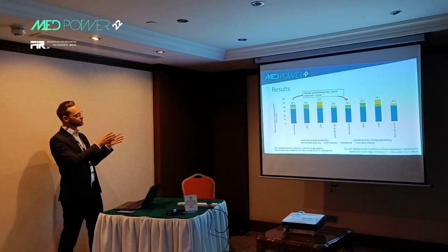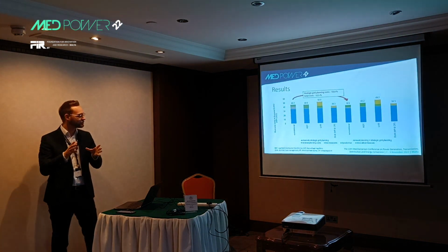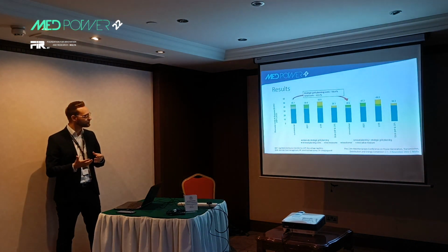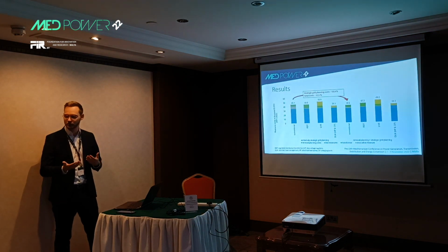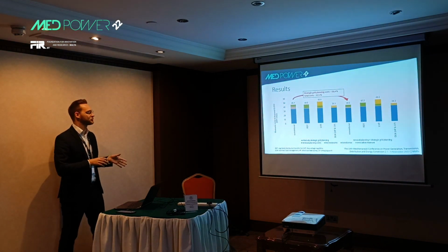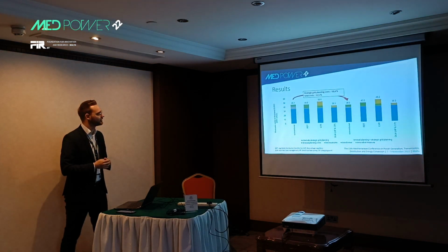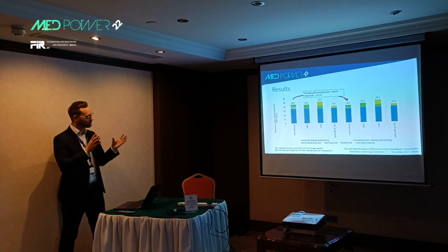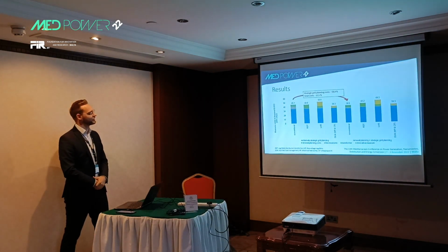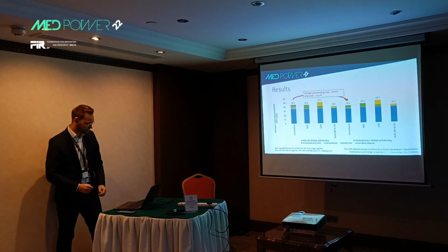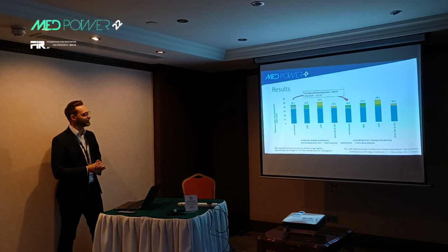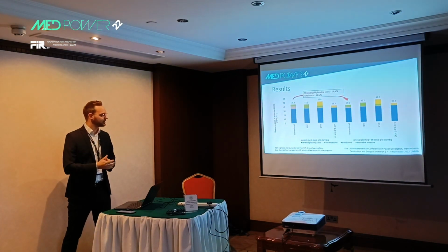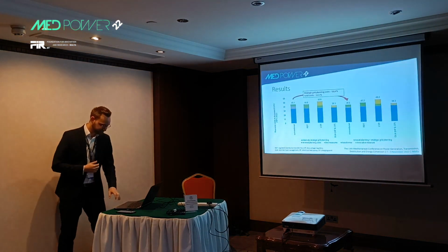But if we use the renewal planning and the strategic grid planning in combination, we can see the costs of the conventional grid planning are reduced, because we don't need all the measures we figured out in the strategic grid planning. So we can reduce in this example the costs by 70%, and the total cost with the renewal planning by 12.5%. Here we can see the conventional grid planning and the dynamic load management are on the same level. So now we can decide which technology is the best for our grid.